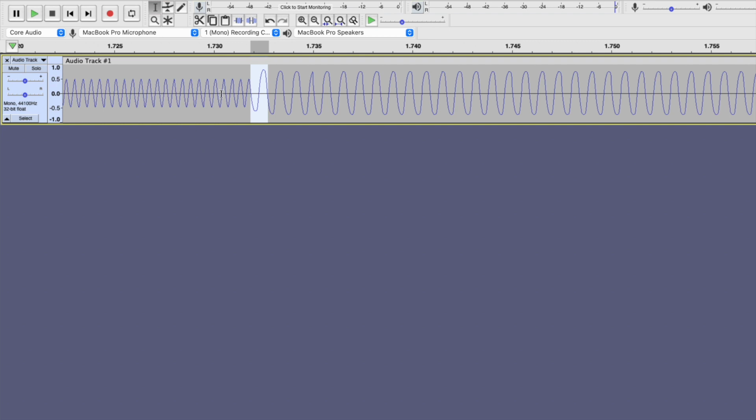Since the receiving software in its most basic form is just a shift register that shifts in new valid bits under a certain period threshold, data isn't accepted until a leader byte of 7F hexadecimal is seen after a minimum amount of ones before. The Kansas City standard specifies a minimum of 5 seconds of ones, but I've relaxed that a lot in my software for now.